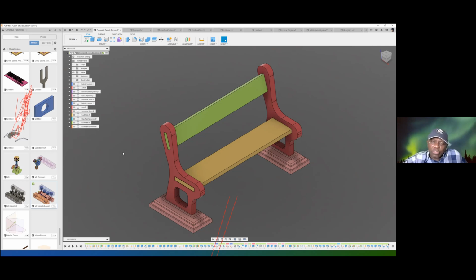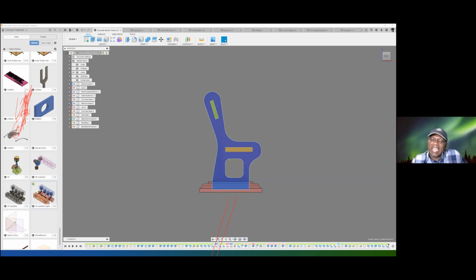Now, I want us to see what happens when we take a look at this thing from this edge. So I will click look at. Now, you can see what has happened. Everything disappears. The only thing you can see is the edge, because this is in orthographic projection where the vanishing point is at infinity, and it appears as if the rays of light are parallel. When the rays of light are parallel, anything that is parallel can only be seen on the edge. So that is one example of a camera setting.